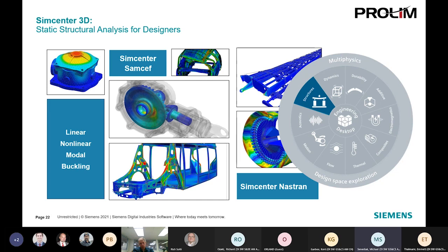Also, things like the modal analysis, you might be looking at, in the upper left there, that casing, and seeing what's the normal mode of vibration of that part. How would that interact if we had a motor on there? Would that be an additive where both frequencies would add together and actually start to cause damage to your structure? Also, those modal analysis results can be driven into a multi-physics simulation for the dynamic response. So we can take that to the next level.